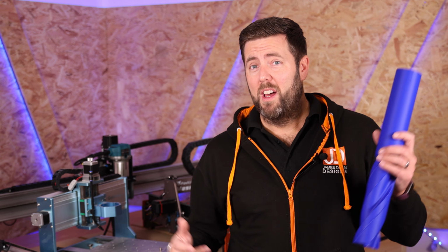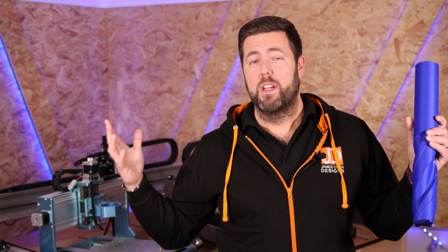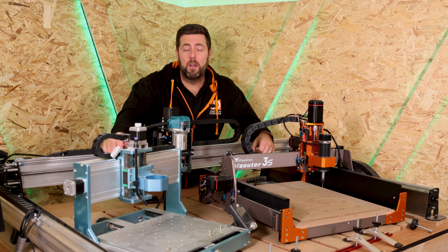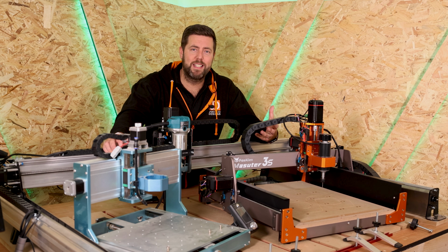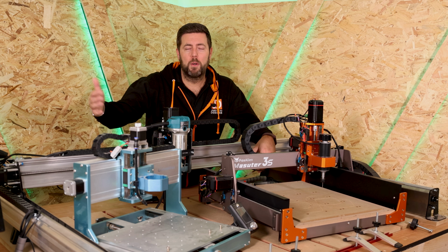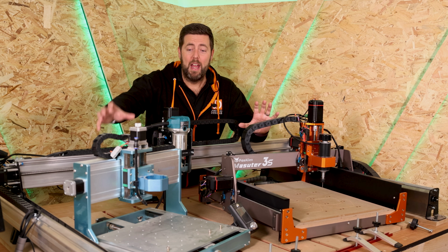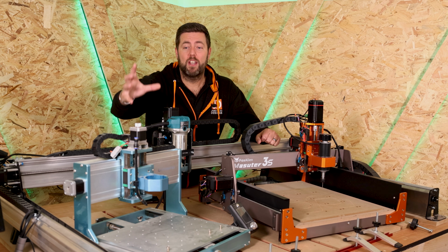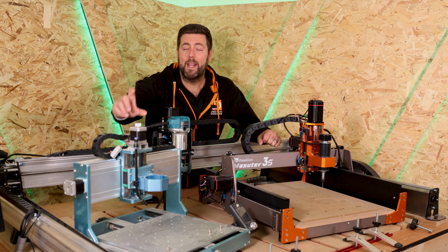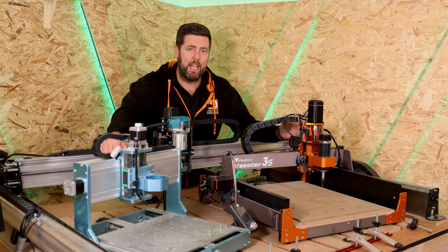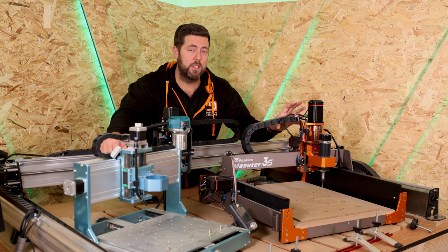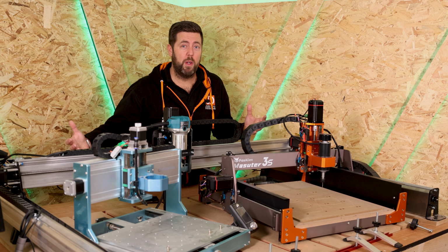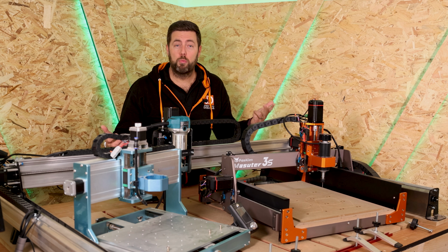So let's set up and I can talk to you about speeds, chip loads, and all the things that go with it. Now, the more you understand about the theory, the easier it becomes later on. But don't worry if you don't understand anything at this phase, because it will become clearer the further that we go through. Now, there are three machines in front of me here. The smaller SaintSmart one is arguably the stronger, more rigid frame overall, but it has smaller motors. The Fox Alien, bigger motors, faster motors, but is belt driven, so it lacks some torque. Then we've got the long mill, somewhere in between, lead screw driven, pretty powerful, pretty rigid.